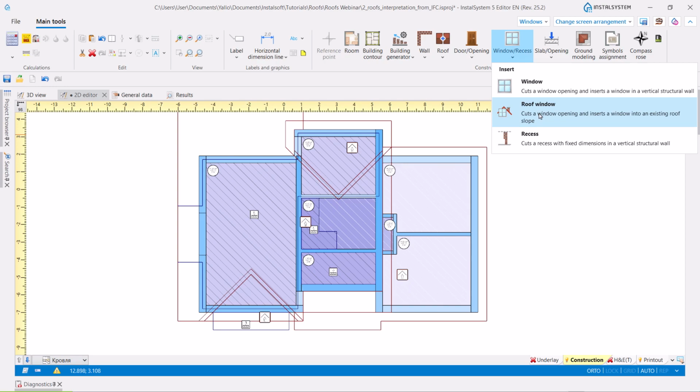First, we need to put a window on the roof which is preferably already ready and calculated and contains no errors. Second, after inserting the window, we do not have to do anything because the program will automatically update our model and also the thermal model after inserting the window and performing calculations of the building structure. And the program will assign the window to a given room.